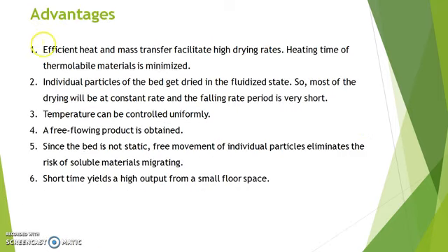Advantages of fluidized bed dryer. Efficient heat and mass transfer facilitates high drying rates. Heating time of thermolabile material is minimized. Individual particles of the bed get dried in the fluidized state. So most of the drying will be at constant rate, and the falling rate period is very short.